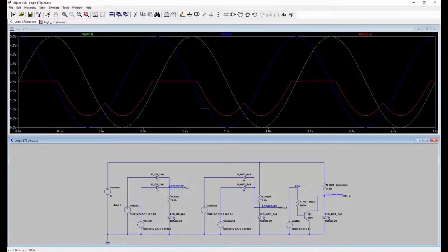But again, we have this very interesting little knock at the crossover point. And the range between this crossover point and a high is only 1.15 volts. So that would be difficult to make. It would be difficult to make anything even reasonably complicated with.